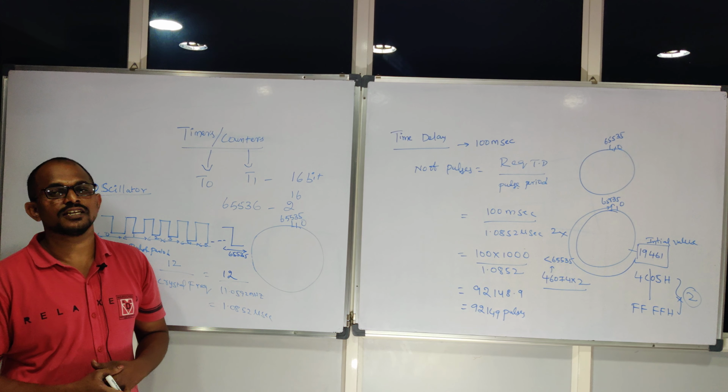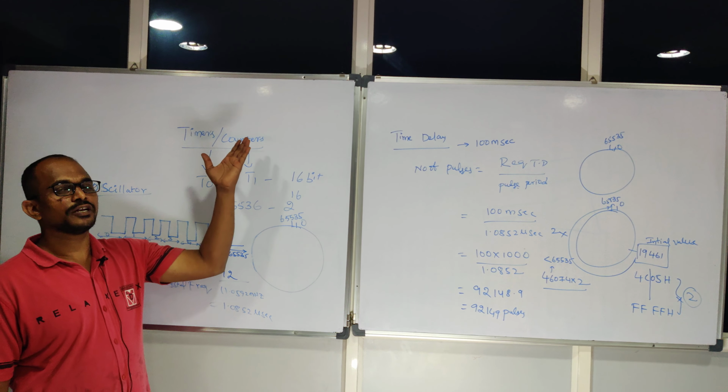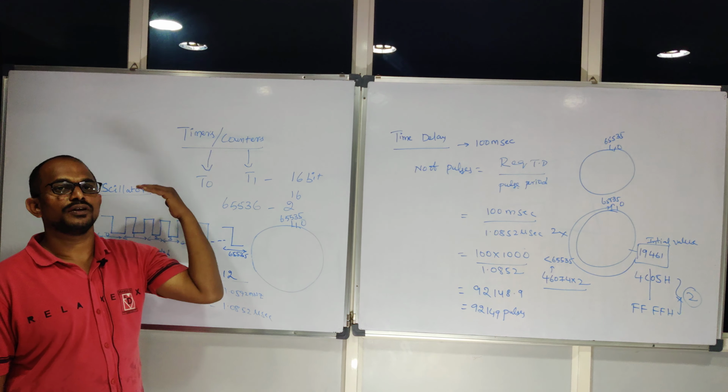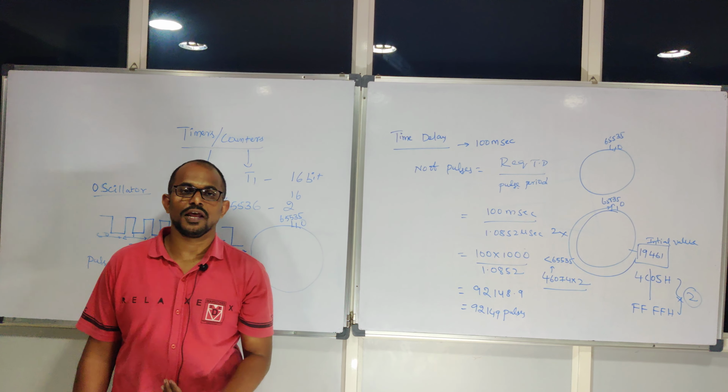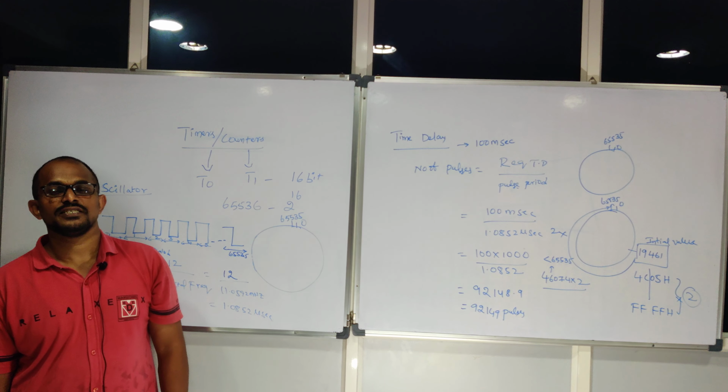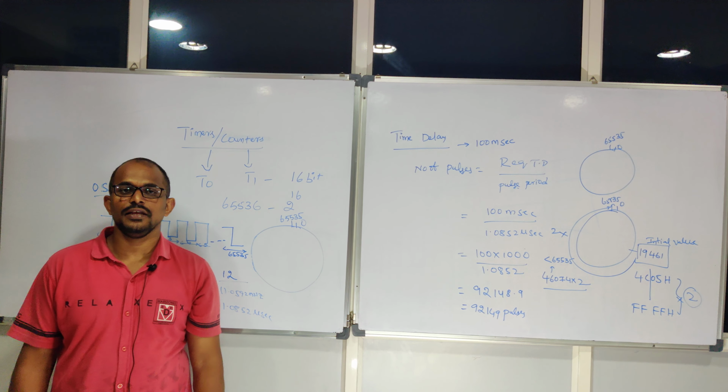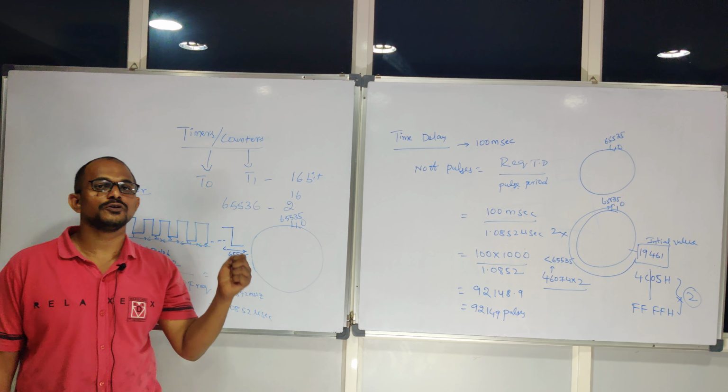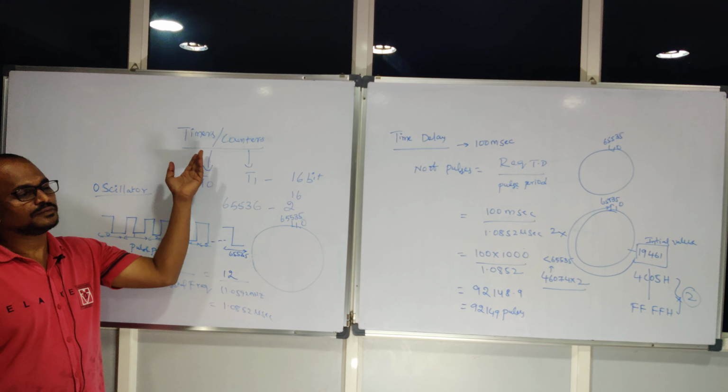So for external pulse counting purposes, you are going to prefer counters. And for accurate time delays, like milliseconds, microseconds, seconds, any exact time delay you want, you need to go with this timers block.